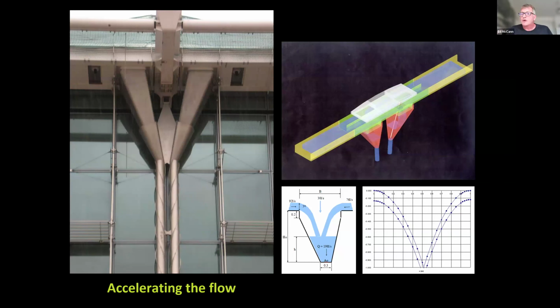And so in this project, it didn't matter that we were meant to be doing the stuff in the ground and there was someone else doing the terminal building. The architect said, we don't want all of those downpipes. If you ever go to Terminal 5 and look up, you're going to see these. That thing running around the top is a 1.3 meter wide, meter deep gutter that runs the entire length of either side of the building. And it's collected into these hoppers, which let the water fall, accelerate, and then get into these 2 tiny pipes.